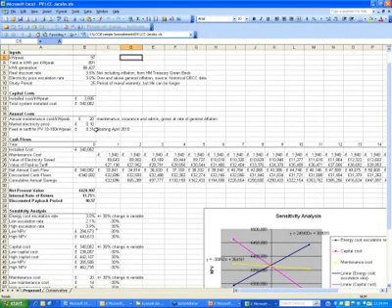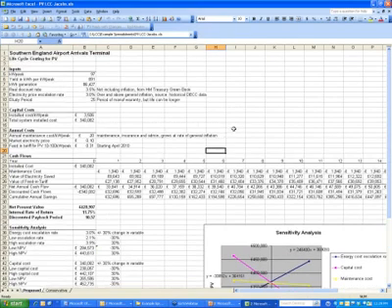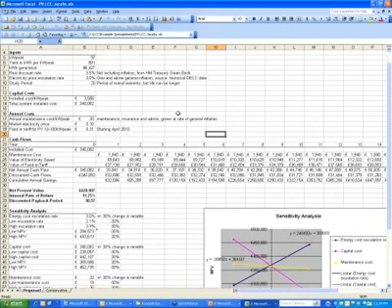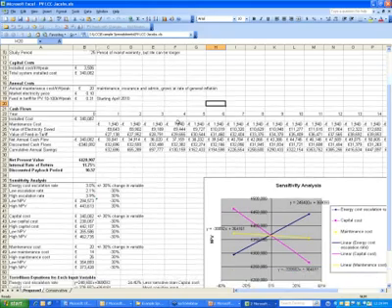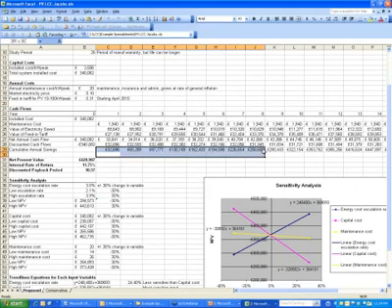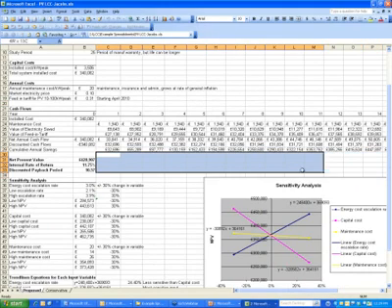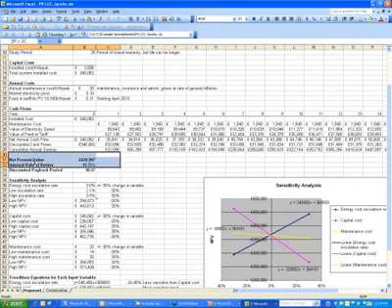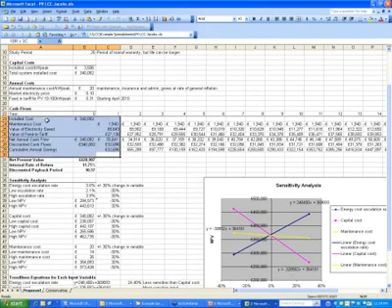So for this size array, we used the feed-in tariff rate, and we found that it definitely had an effect on the payback, more so than CRC would. And I realized that there have been some issues with whether the government's going to continue at what rates. But basically the point is, if there's any kind of subsidy available, I would recommend getting that into your analysis and quantifying it, saying what that benefit is.